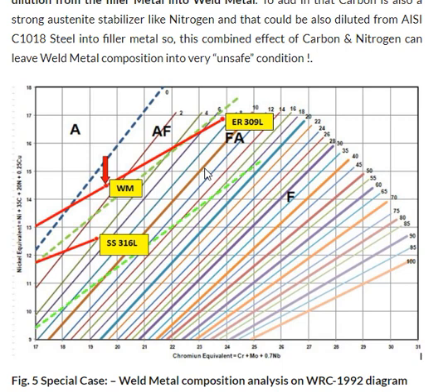We have to maintain the heat input as low as possible, because if we get the ferrite number less than 3, the primary solidification mode will not be ferrite, there will not be traces of any ferrite, and the primary solidification mode will be austenite only.